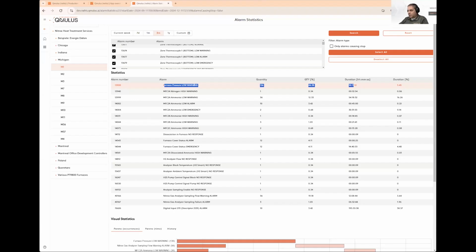For someone who's not aware, first of all, it's a warning, which means the pressure is suggested to be a little higher than this number. That's one. Two, deviation on my pressure transducer will easily give me this. So I'm not so worried. I should actually exclude this or make my tolerance a little bigger. I think this is more of a nuisance that I should address than an actual problem. This has nothing to do with metallurgy.